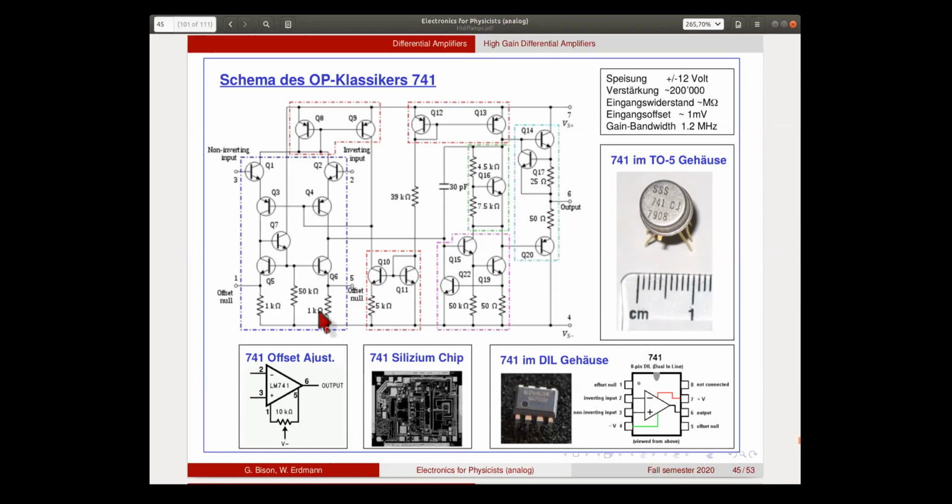For a real world amplifier, it's important that you can make sure that the offsets are small, and this one actually has the way of modifying these offsets with external pins. So this we never used, of course, in our idealized amplifiers, but when you have a real system where it's important to compensate these offsets, then these operational amplifiers sometimes have these inputs that can help you with external resistors to modify these current mirrors to make sure that the offset goes away.